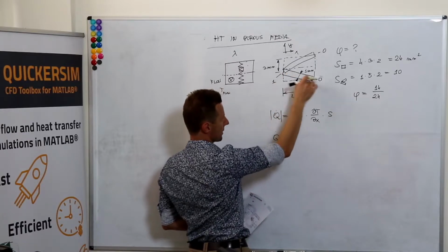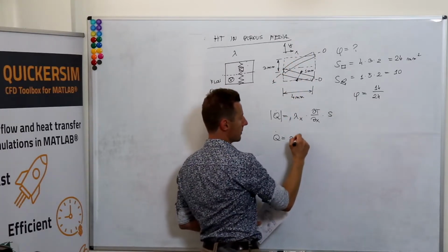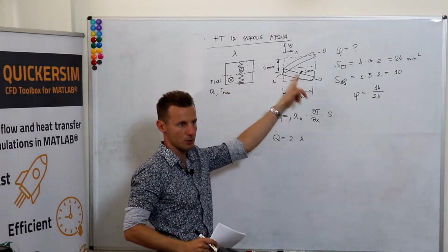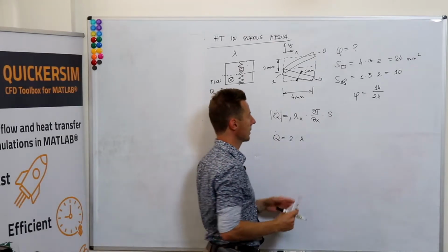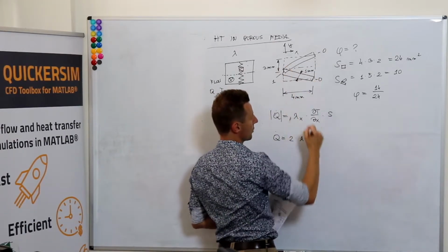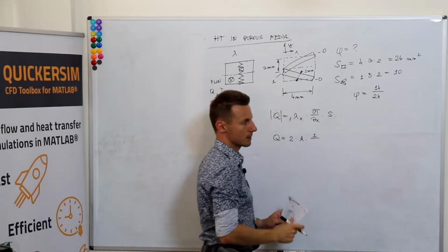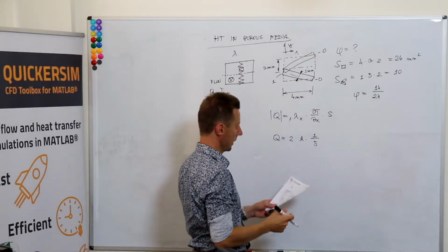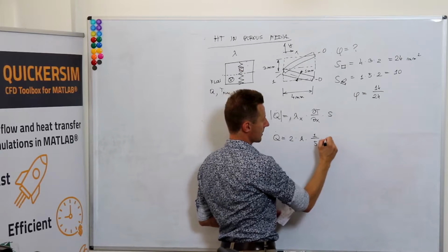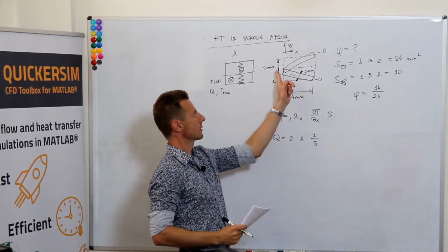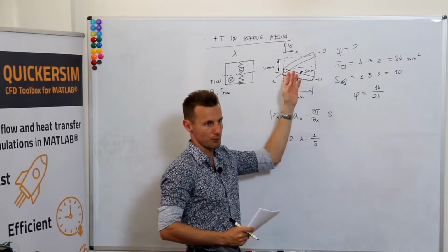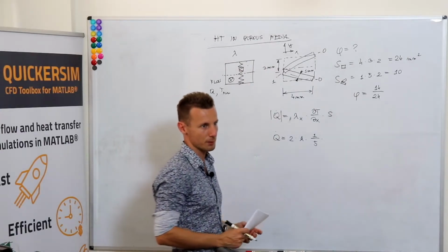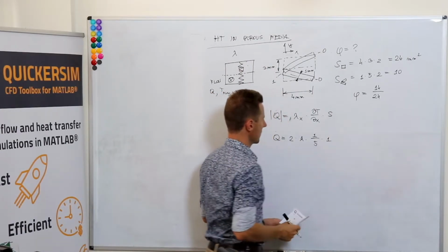Well, first, we've got two fins, the bottom one and the upper one. Then times thermal conductivity of the material, of the metal sheet that it's built of. Times, well, okay, temperature difference is 1, divided by length is 5, and times surface area, so basically thickness of each fin, or if you prefer, times the dimension in the third direction, but we can clearly omit that. It's something like that.